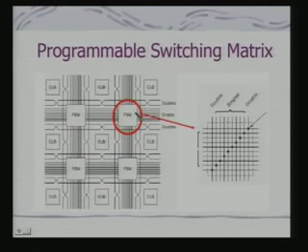And this becomes a programmable switch. This is a programmable switching matrix, which connects the different CLBs together, and I can load data onto this matrix to decide on the interconnection, and maybe also for configuring the CLBs, because that would provide various kinds of control input. So, it will come from one CLB to another, and it can be an input as well. So, this switching matrix determines the interconnectivity between the logic modules.